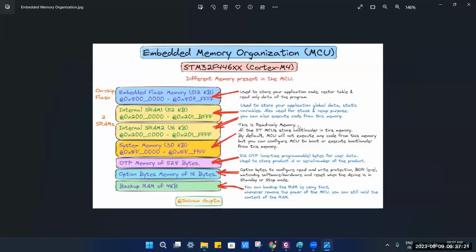No, I'm talking from the point of view of security. For example, you have a secure system which is running with secure boot. So why do you use secure boot? To ensure that whatever updates are coming into the system are validated and authentic. Let us say I conduct a man in the middle attack and send some malicious firmware. When it downloads it, it will first do an integrity check, maybe ECDSA and RSA kind of check. Then it will check the encryption, and then validate whether it is actually authorized or not. If the encryption keys don't match, it will not execute that; rather, it will stop executing that particular firmware.